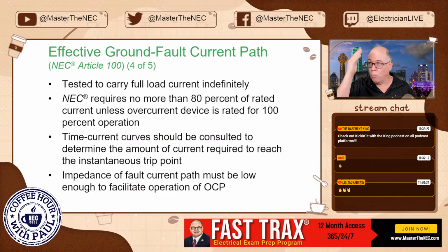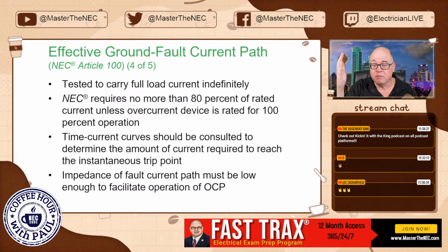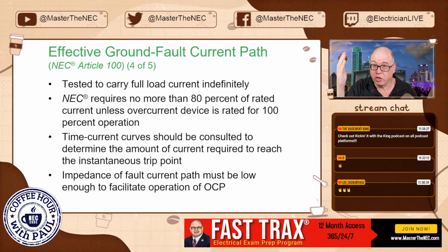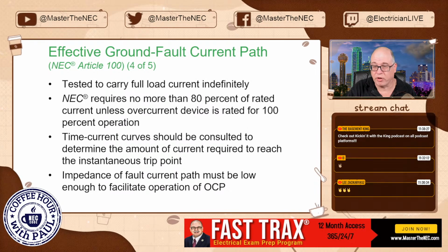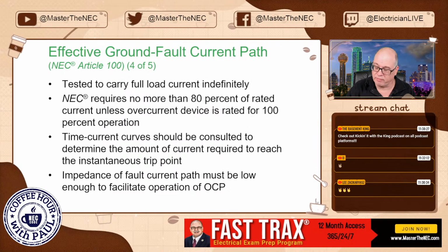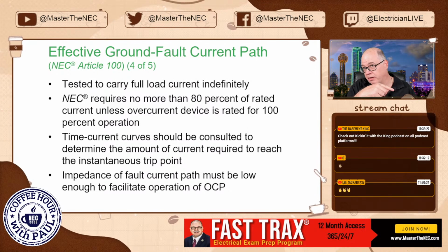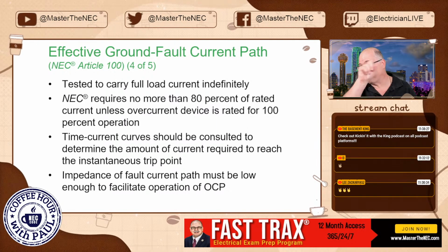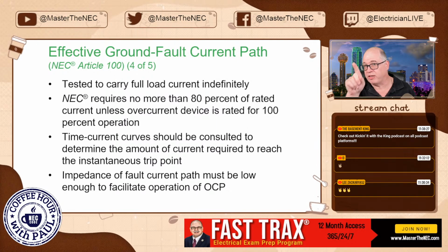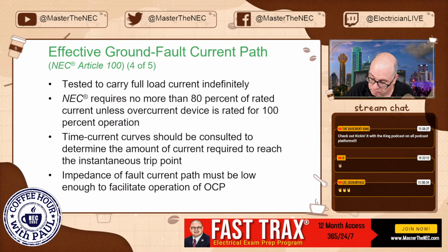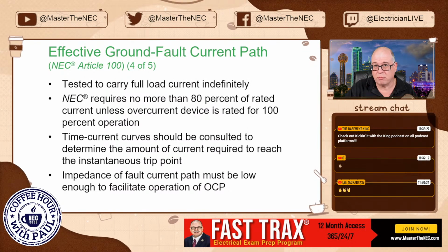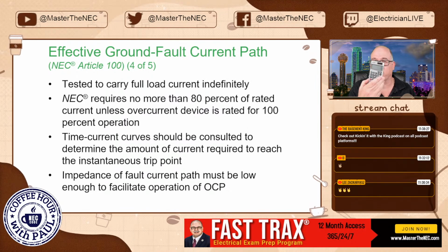So at any rate, if you've got the breaker, then you're going to do what? If it was a 20 amp overcurrent device, let's do the math. You want to find out what the current limit is of a conductor so that the continuous load is not going to exceed the rating of the device: 20 times 0.80 is 16 amps.